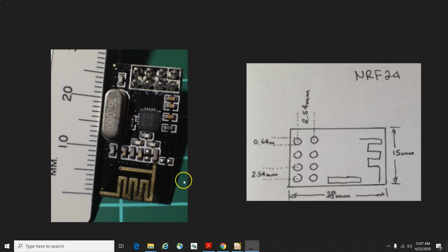Here the important things are the circumference of each pin, the distance to the neighboring pins, and the clearance from the edges of the board, etc. These are very important when designing custom footprints. You can get them by looking at online documents for the particular part, or if you have the part with you, you can use the ruler to do the measurement.